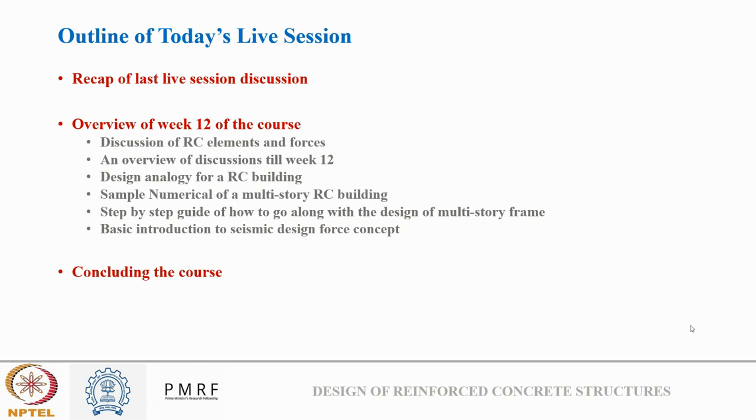Then we will see some design analogy for an RC building, like if you want to design a whole RC structure, what all analogy you need to keep in mind while designing. Then we will see a simple numerical on a multi-story RC building. Today we will see an office building, and I will guide you step by step on how the thinking generally runs if you are asked to design it. We will also have a basic introduction to the seismic design force, IS 1893, while we do the designing. Finally, we will conclude the course and the session.